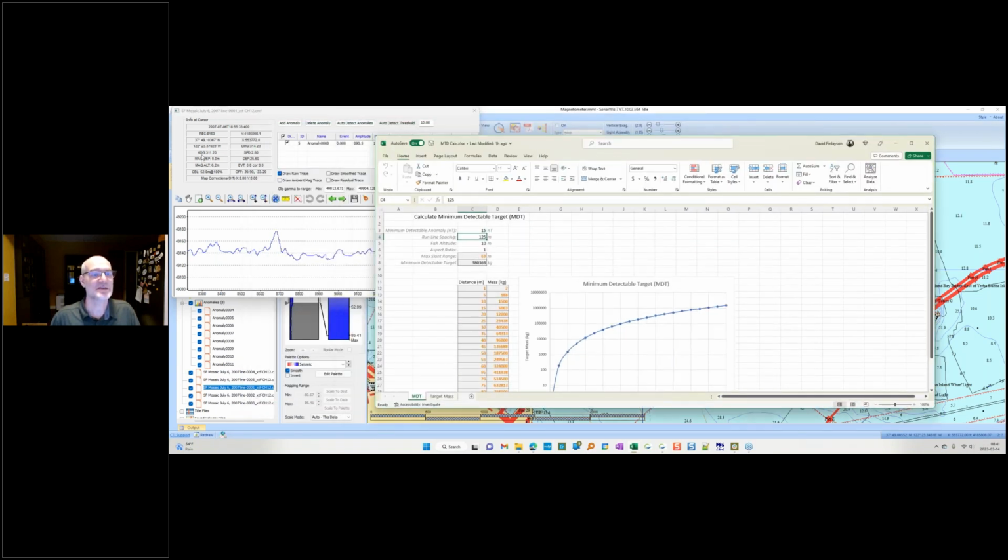And the survey was run with it. Looks like the altitude is around 6 meters here. In the other parts of the survey, it was around 10 meters. You can kind of see how the fish altitude, the magnetometer altitude, is changing. Let's try putting in 10 meters there, and then we'll use 1 for the aspect ratio.